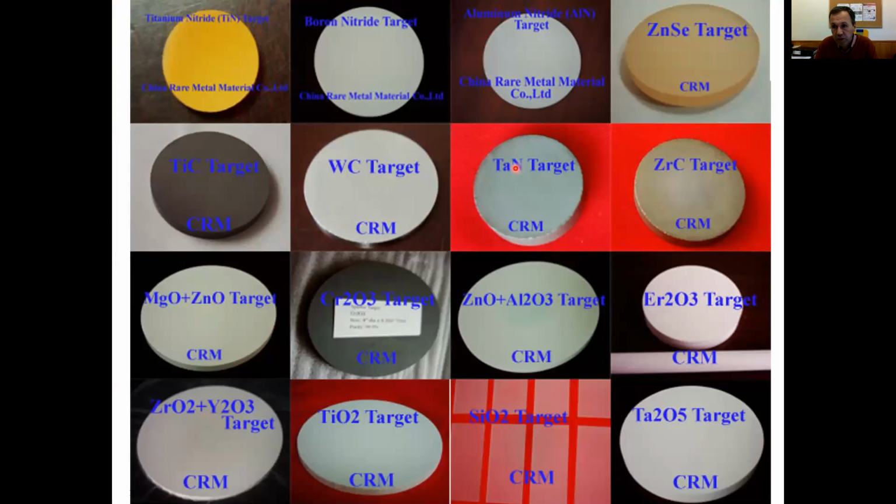a tantalum nitride target, which is important to provide coatings, for example, for dental implants. Because if you make tantalum nitride coatings and they are porous, they can be a base coating for putting a ceramic material on top of it afterwards, for example, hydroxyapatite. Hydroxyapatite is a calcium phosphate material which resembles very closely the structure of bone materials, specifically what we have in your teeth.